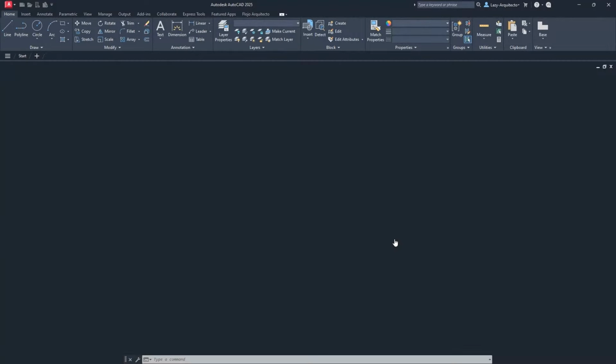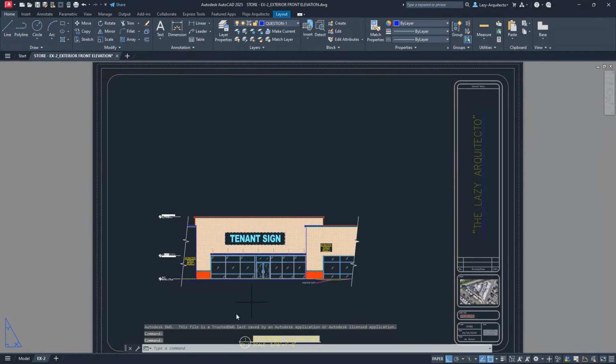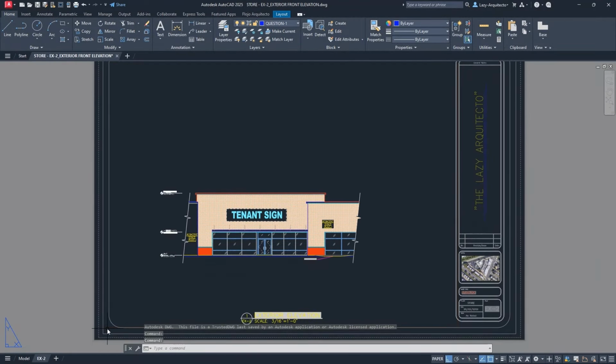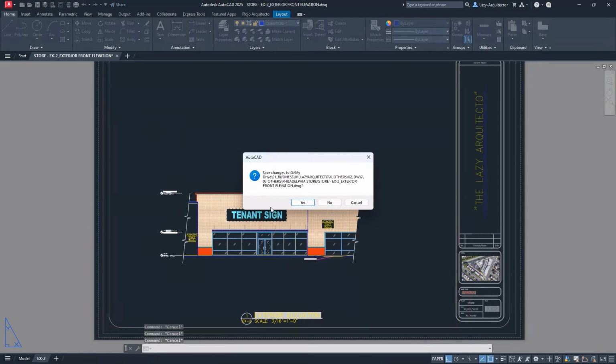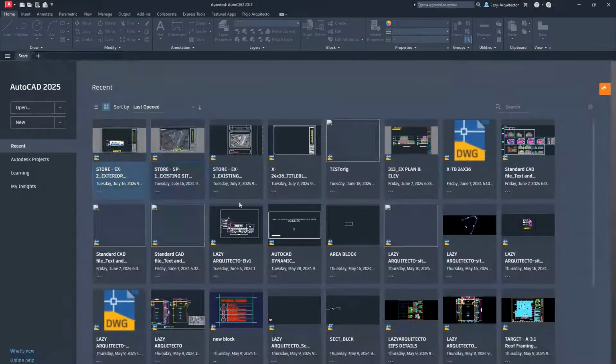Right, I can close that out, and you're gonna see that, of course, if you open a different drawing, you're not gonna have the drawing scales over here that you just created. If we check here, you can see that the civil scales are not here, because when you create a scale, it's only saved on that actual drawing. But since we are streamlining this, let's continue.